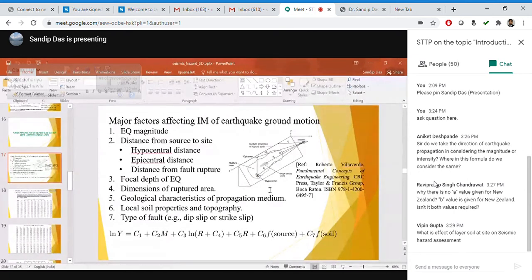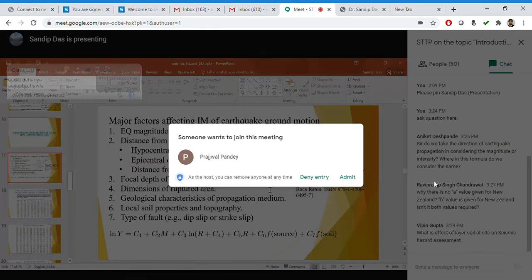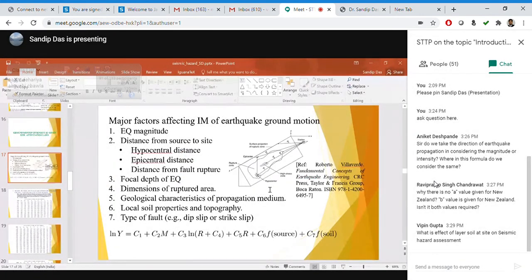Unless you get a complete catalog for every magnitude range, because when you are using your GR relationship, it is magnitude exceeding a certain value, right? So for every class of magnitudes, your catalog should be complete. Now if the number of years of completeness is not very long, then you will not get a stable estimate. Once you are talking about the average annual rate, you must have at least a good number of annual rates over several years. Then only your estimate will be stable. So how quantitatively sound it is will depend on the earthquake catalog.